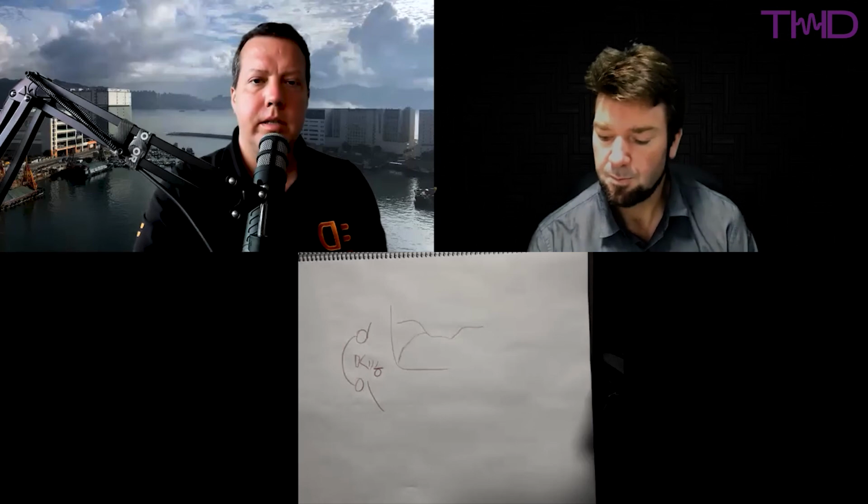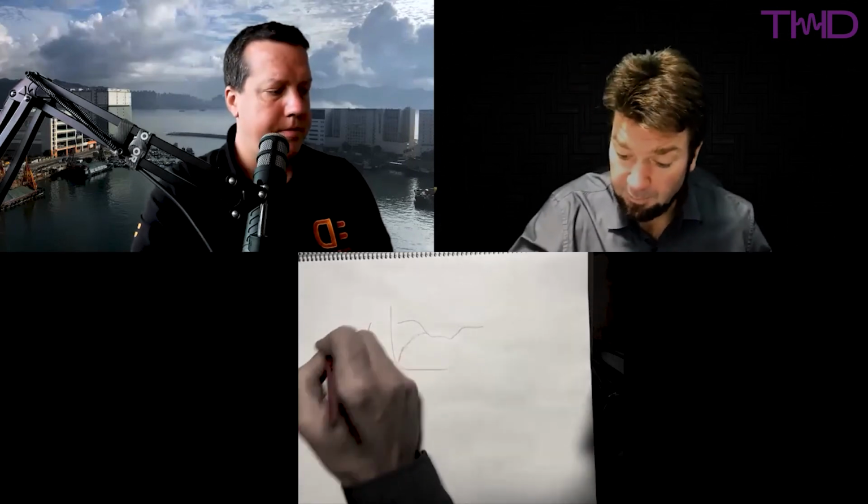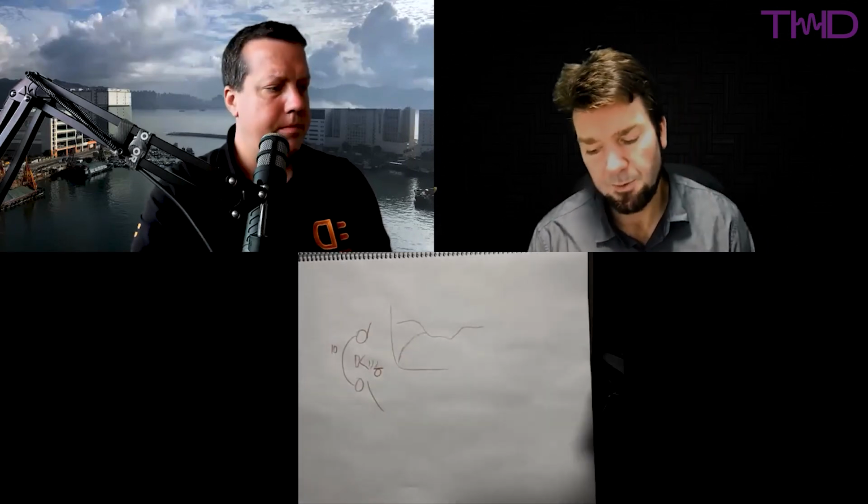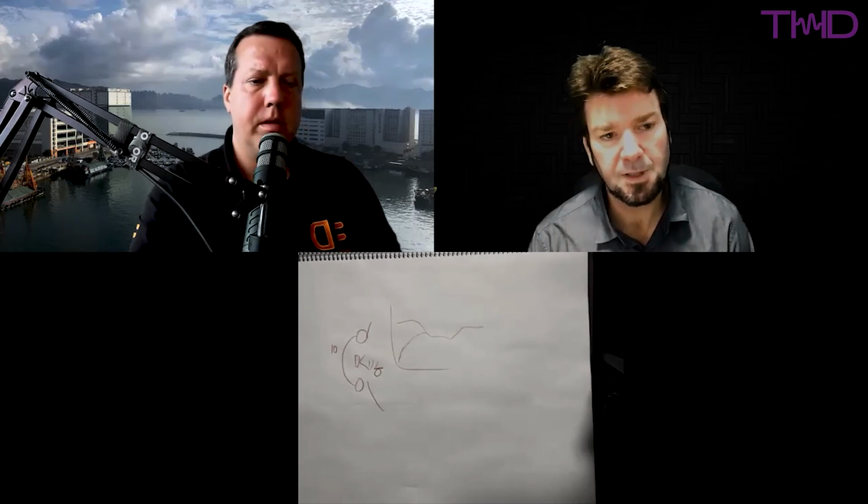Right. Got it. Okay. As well as a feed-forward microphone. I don't think you can do it without an internal microphone. I think there's no way to know what you should be changing to unless you've got an internal microphone for adaptive. Okay, so I guess the adaptive part is just the tuning of the ANC depending on what that mic is picking up. I mean, open it up to free air, it's a totally different thing than if it's a sealed cup. Yeah. So the original ANC headphones all used an analog electronic circuit to create the filter.